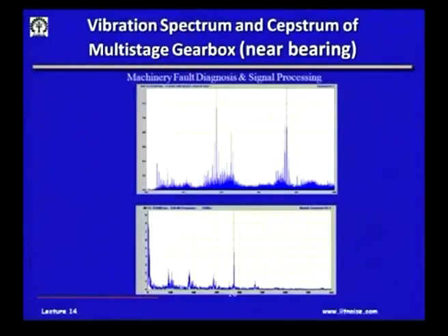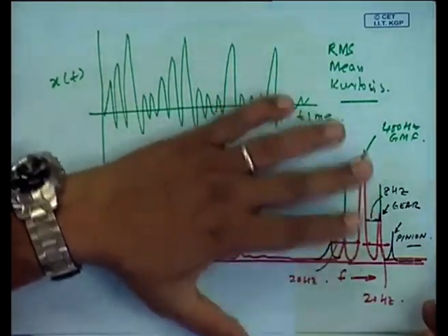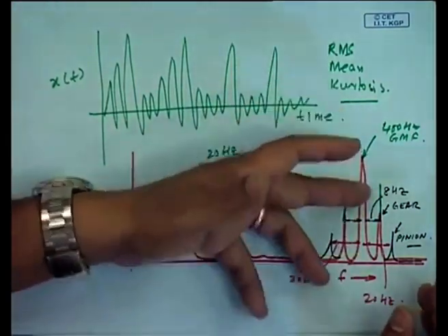So, pinion is at a fault, and that is the power of Cepstrum analysis. So, sometimes if you have done a good measurement, a good kind of frequency analysis, if you have a good delta f, you can do a good resolution, and then you may be able to distinguish them. But Cepstrum otherwise is a very, very powerful technique to determine modulations in signals. Okay.